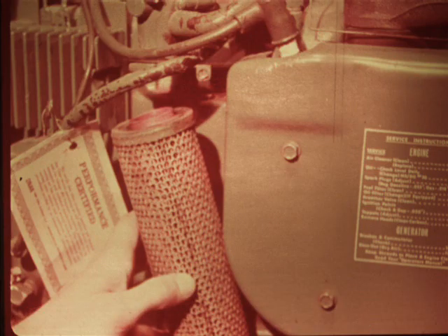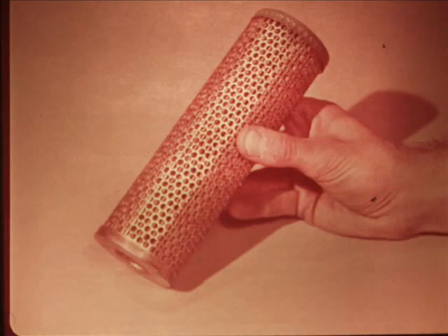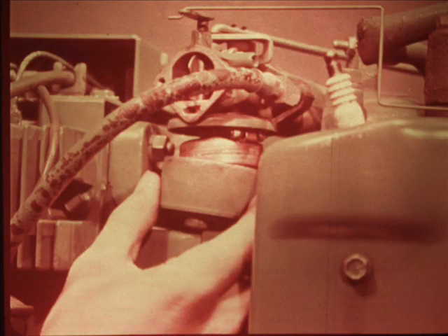Remove the air cleaner element and inspect it for restriction from dirt buildup. A restricted air cleaner is a major reason for a loss of power under load. Tap the air cleaner base lightly on a flat surface to clean it. However, you should install a new element if it doesn't become clean or it has over 200 hours of service. Next, remove the float bowl from the carburetor and inspect the float and the needle valve.